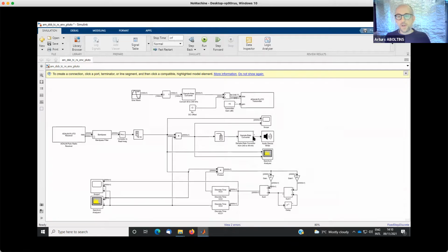And it works much better if it puts those samples one by one here. So it will be like the real bottleneck in the model. So this is unbuffer and buffer, because the PLL cannot work with packets of samples. It needs samples one by one.